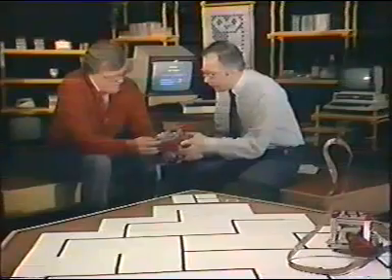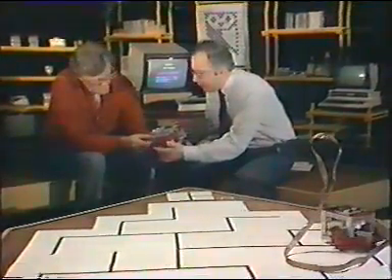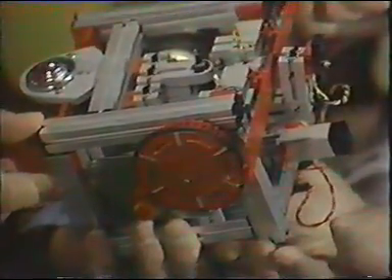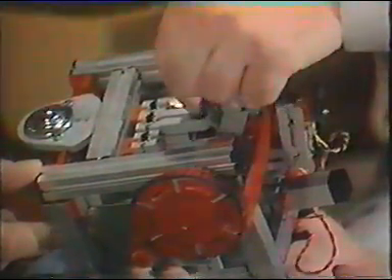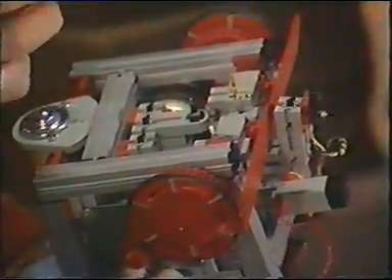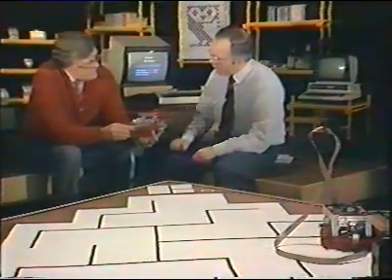Well, those are the input devices, and we've also got some output devices here. Right, well, we've got two output devices. There's a stepper motor here and a stepper motor over here, and as well as that, there's a device for moving the pen up and down. So, stepper motors and pen up, down. The stepper motor just moves it around one click at a time at about 7.5 degrees. When you give it one digital pulse, it moves, as you say, a very small angle.